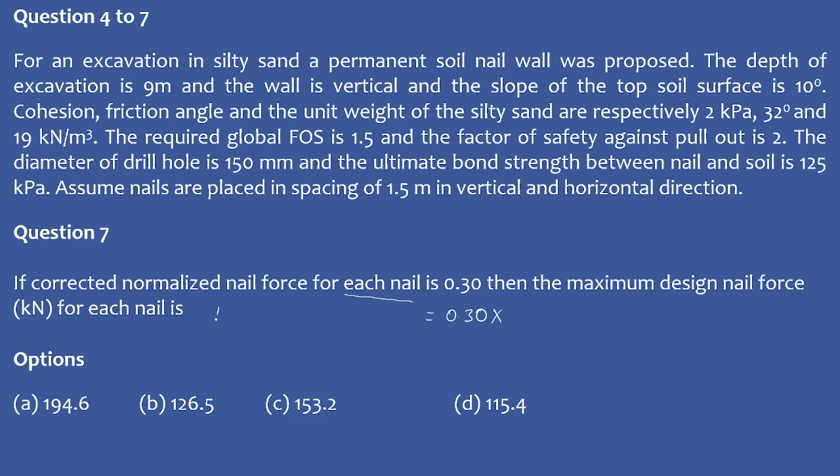The maximum design nail force is given by tau normalized into gamma into H into spacing in the horizontal direction and spacing in the vertical direction.